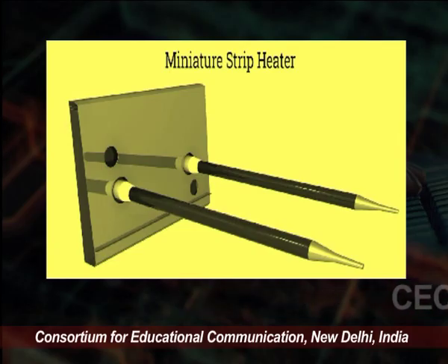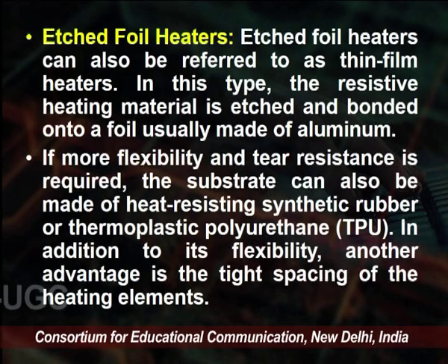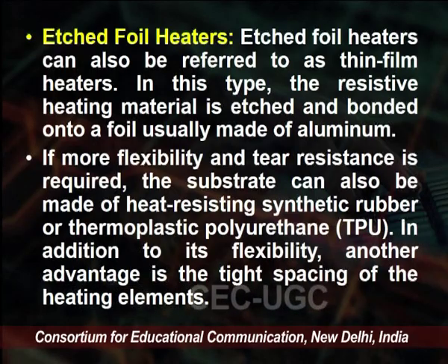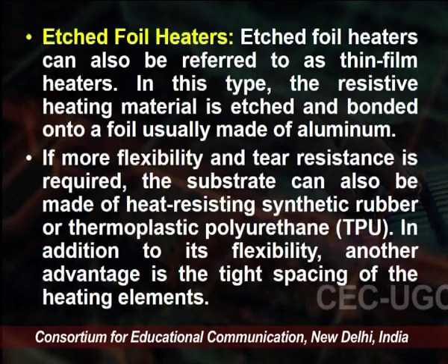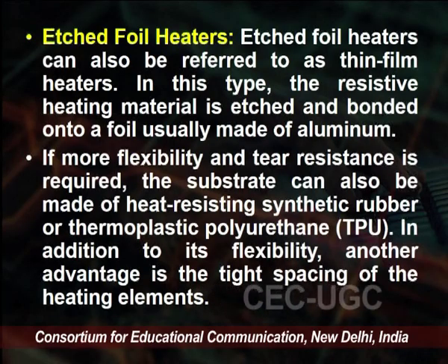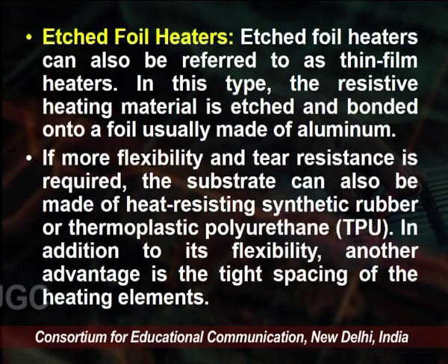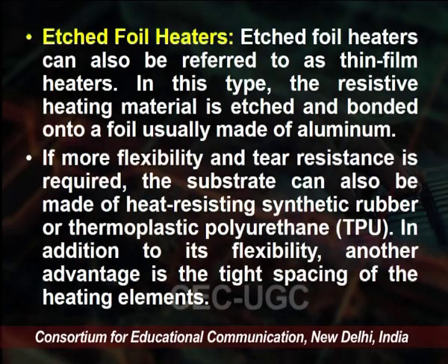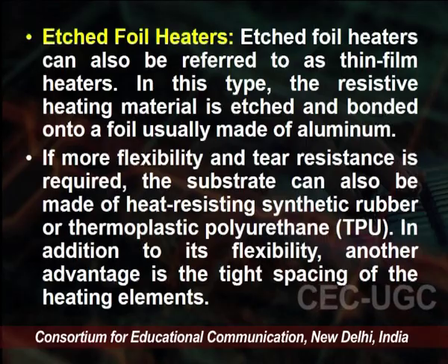Another type of heater is the etched foil heater. This type of heater can be referred to as a thin film heater. In this type of heater, resistive heating material is etched and bonded on a foil, usually made of aluminium. If more flexibility and tear resistance is required, the substrate can also be made of heat resisting